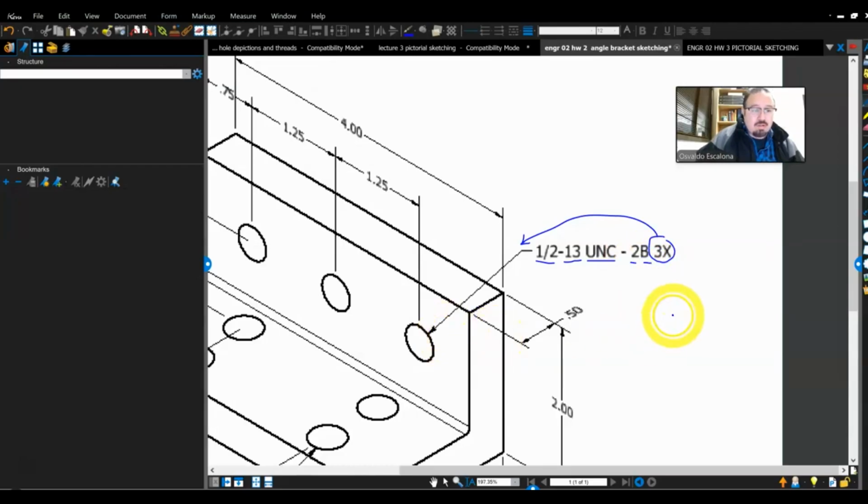When you go and draw it, you don't have to actually go look in the book and find out exactly what the diameter is, especially the minor diameter, because you are drafting it on paper, with hand sketching, so you will never get that accurate. So when you make your major diameter, make it half an inch, and when you make your minor diameter, just try to make it smaller. Make sure you have a nice line weight, line thickness. Remember, none of the dimensions. This is not a dimension drawing. Just come up with the views. All right.